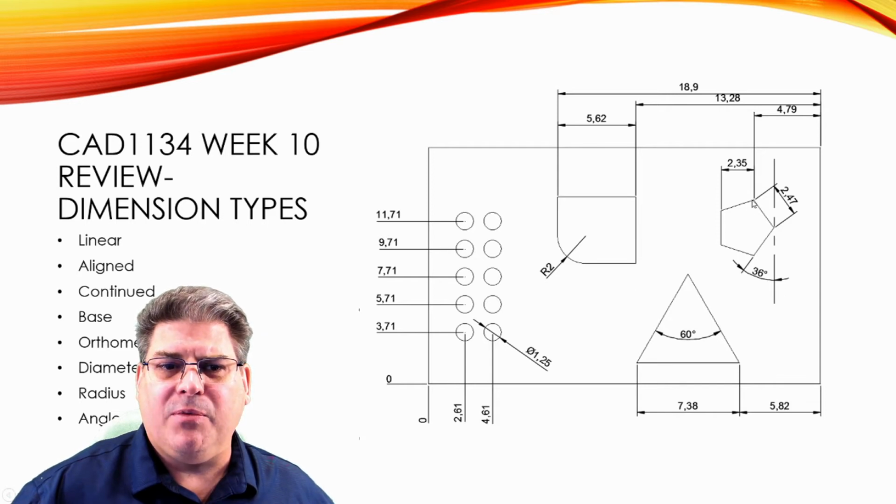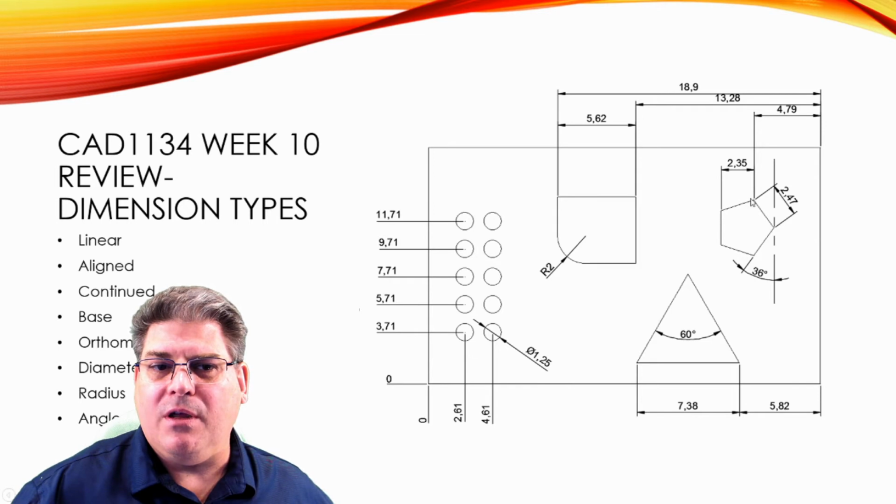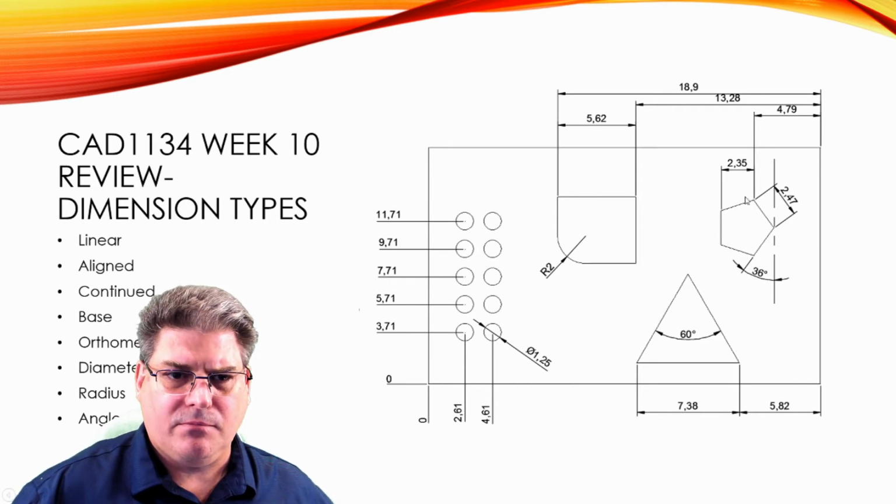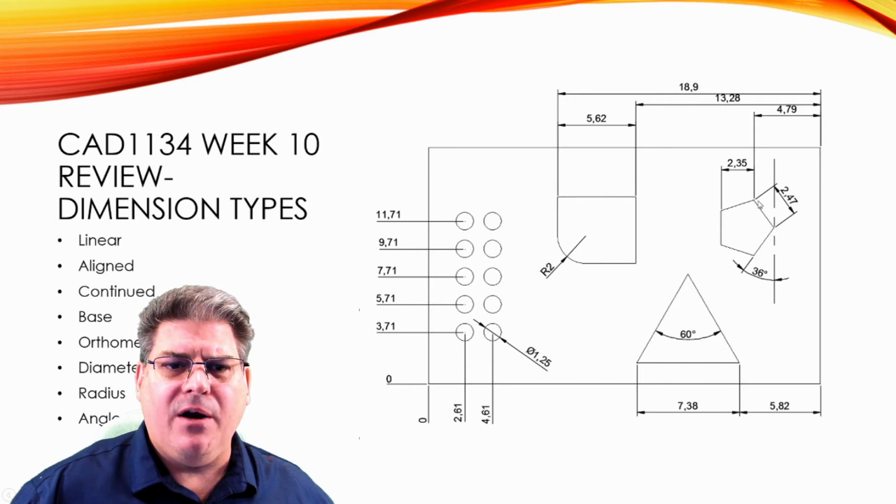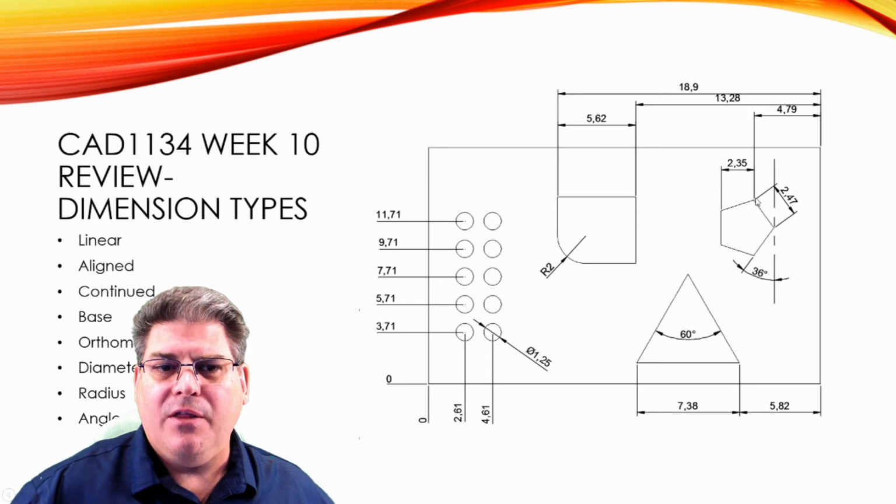In this case, it's a perfect example where I have a sloped line, and I don't really care. I'm measuring the width of that sloped line, so across, not the hypotenuse, but what would be the adjacent. Now, this one here is aligned, so this is an aligned dimension, and it absolutely measures the line that comes across here.